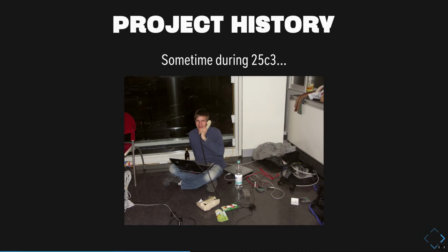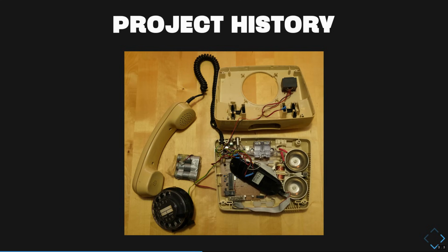And then, my project has some history as well. At 25C3, I took my first prototype with me. That was still made on perf board. It used a Siemens S35 with AT commands to dial. This thing here is a transformer that is operated inversely, like a normal power supply transformer, to generate the ringing voltage. So, everything worked and it was quite nice, but I wouldn't want to give that away as a present to people who are not in tech or don't want to tinker around with such things. And this is why I chose to make a version 2.